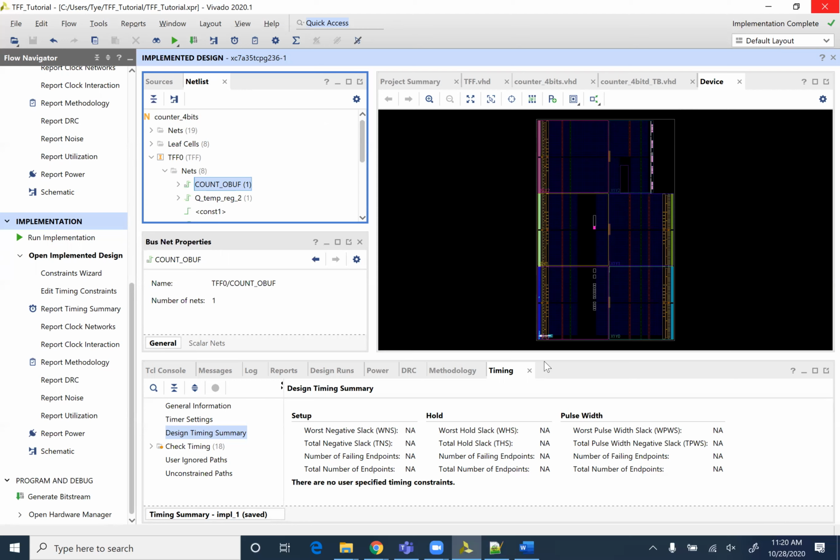If it is not unwrappable, like if loop 2 requires an output value from loop 1, the FPGA isn't going to implement that in parallel logic. It's going to implement it as a cascade of logic that is just waiting, similar to a ripple adder. And if your loop goes for 100 or 1,000 or 10,000 iterations, which is not uncommon, you can get into some serious trouble.